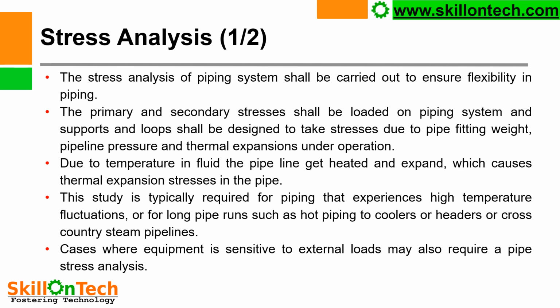This is a pre-activity prior to fabrication. The primary and secondary stresses shall be loaded on the piping system, and supports and loops shall be designed to take stresses due to pipe fittings, weight, pipeline pressure and thermal expansion under operation.